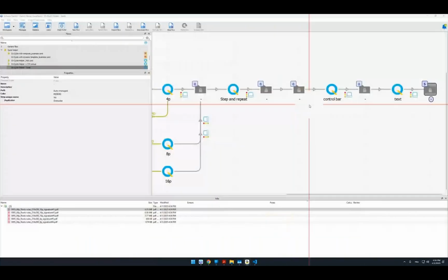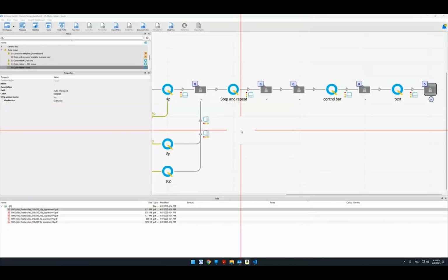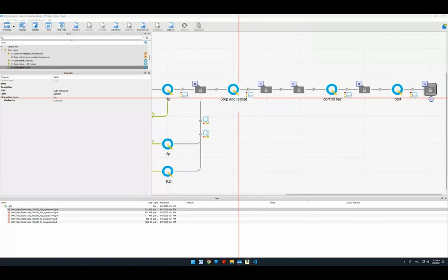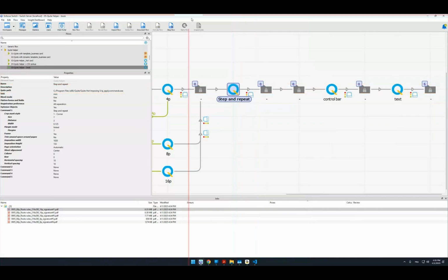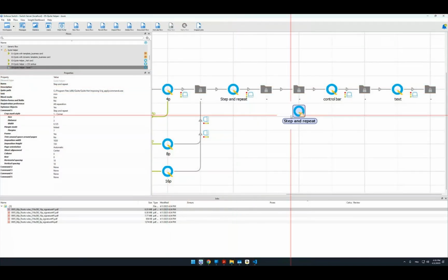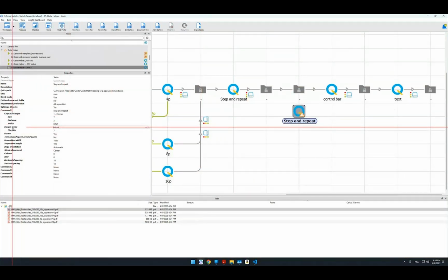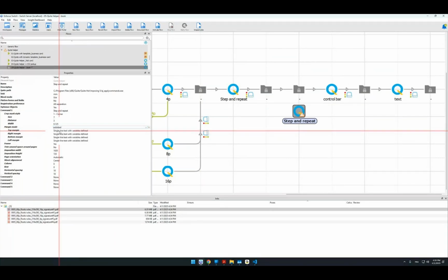could there be different sheet margins for the horizontal and the vertical? Sheet margin for the horizontal. So it's Magnus, I think. Yeah. For the left side, top side, right side. I think so, Vigo already responded, yes, you can set margin mode to unlinked, but you have to choose a page orientation. Yeah, it's linked, and you can create unlinked ones and just put variables in here.